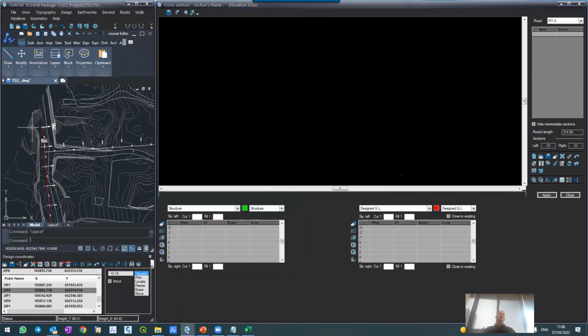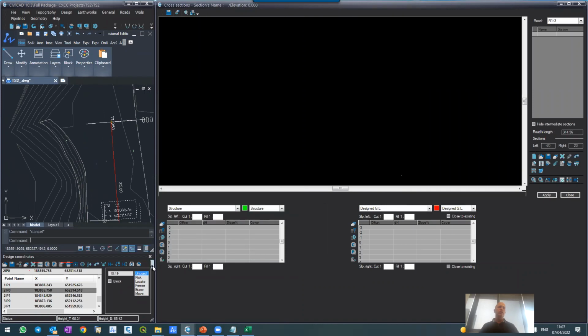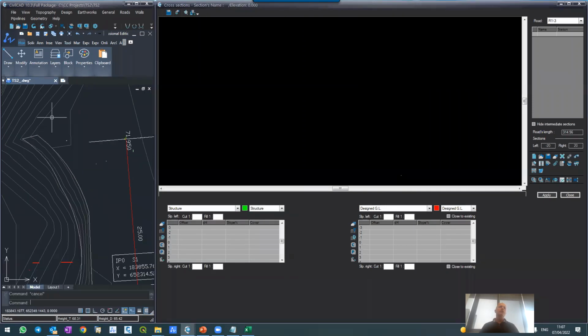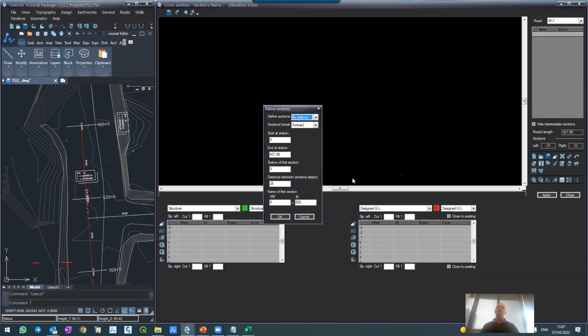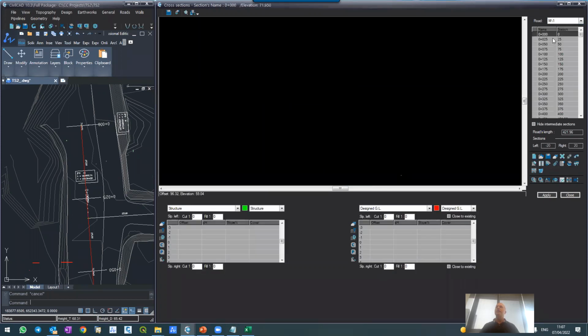Okay. So now I'm on this road that we see on the right, on the left, and I want to design the cross section. So first, sorry, I'm on road number M. Let me move to road number M. And what I'm going to do, first of all, I'm telling the software, split the road into 20-25 meter intervals like we know. So we have the table, show the table. So we see, we have the list of cross sections here on the table. So I'm standing on the first one, this one.